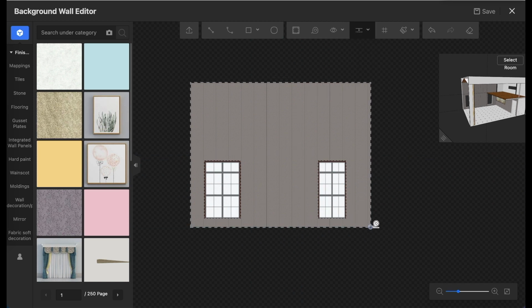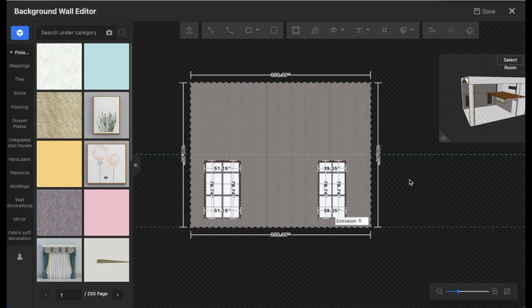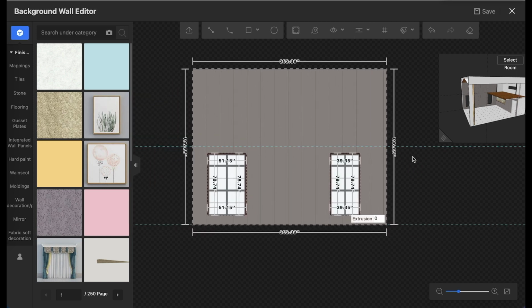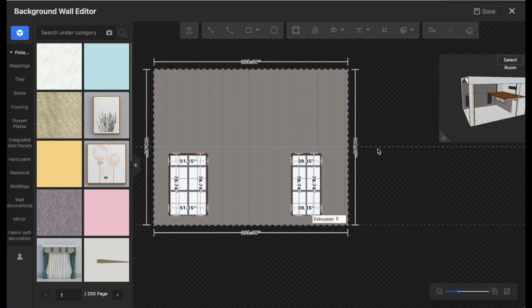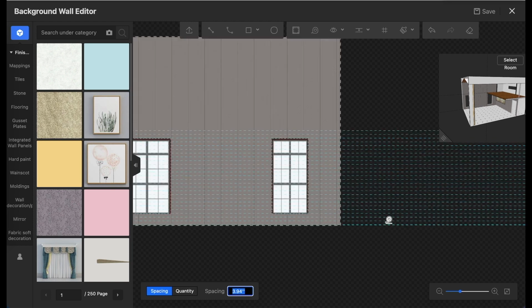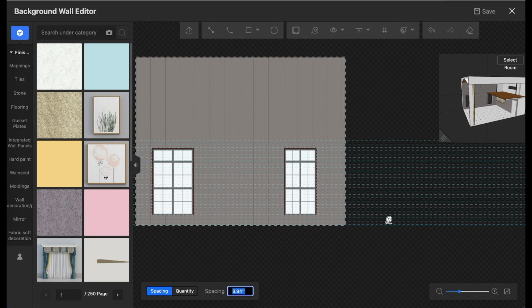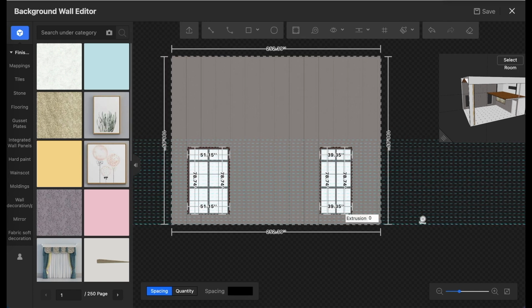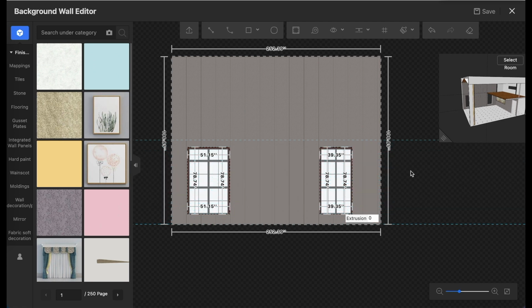Let's start from the guide here. Okay, and here we're going to type in 98.94. And there you go. The reason we're doing this in the wall editing view is there is a really powerful feature called array. See what's happening? The array tool is going to help us tremendously in creating even spacing, to determine the basic dimensions of each tread height of the stairs.